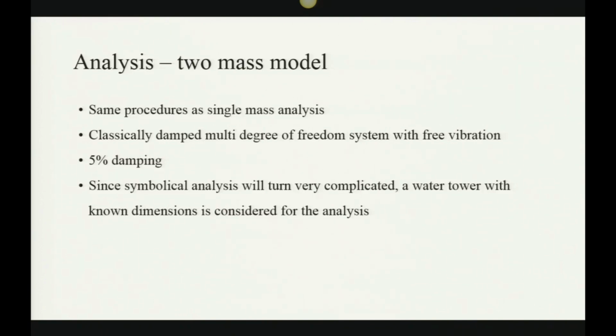We analyzed it as a classically damped system with multi-degree of freedom and free vibration. We consider 5% damping. And since it was very difficult to analyze it symbolically, we actually came up with some numbers. We considered a tank of 12 foot in radius and a supporting structure of 80 feet. And then we went with that and started analyzing our system.